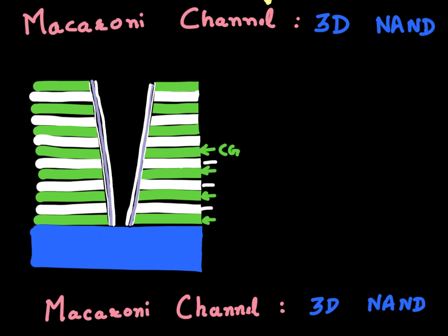my gate stack. So I might have an oxide, a nitride, followed by another oxide deposited inside this plug first, and then would come the chance where I need to fill it up with the polysilicon which will form my channel.